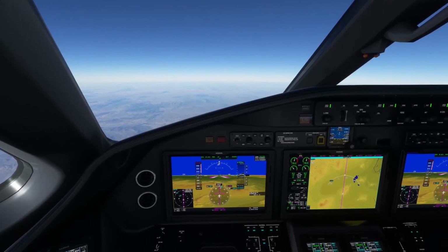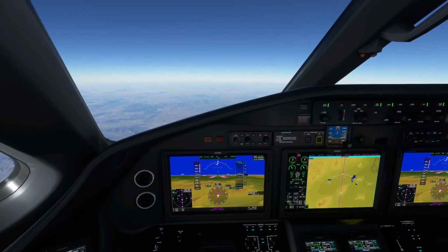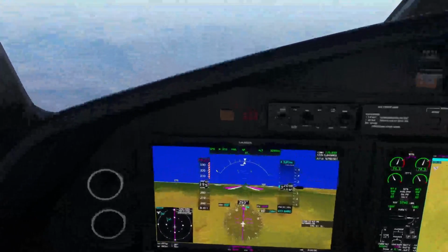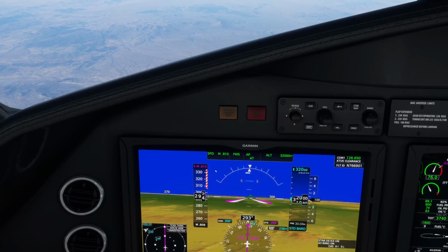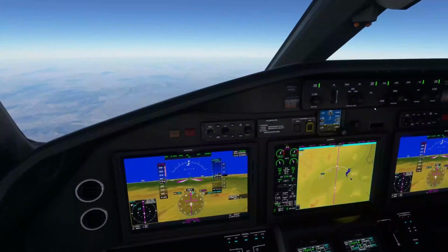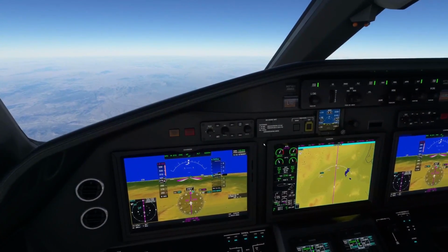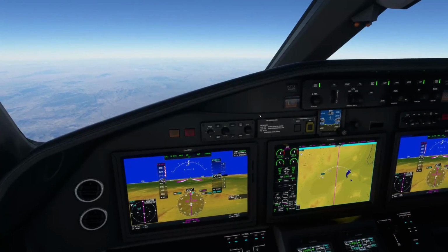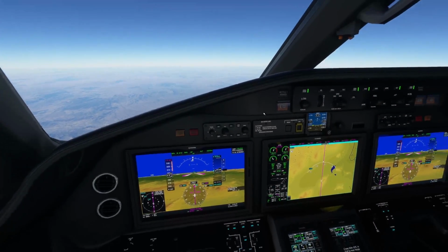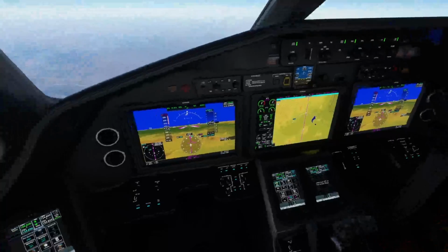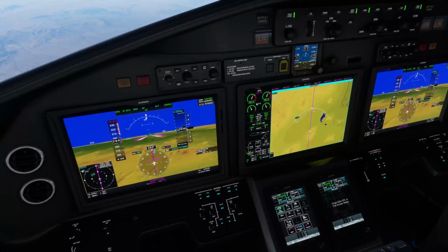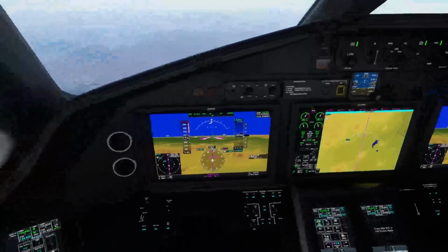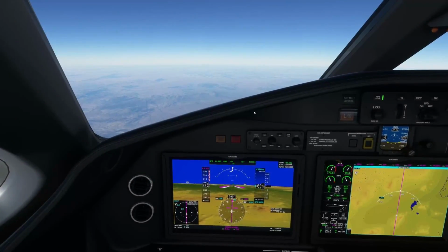We're getting a little bouncy up here, aren't we? And you can see also automatically the speed rating changed from indicated airspeed in knots to Mach rating. Before, we used to have to manually change that right around between 25 and 28,000 feet. We don't have to do that anymore. So that's also really nice as well. See what engine performance is showing, about 80% there is target. Airspeed's maintaining 294 knots. I'm pretty happy with this, guys.